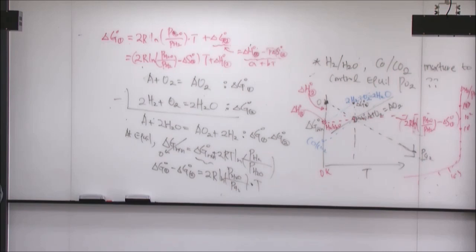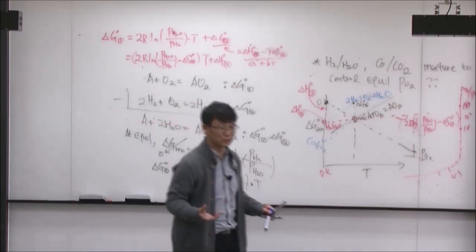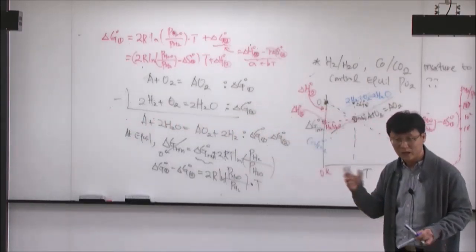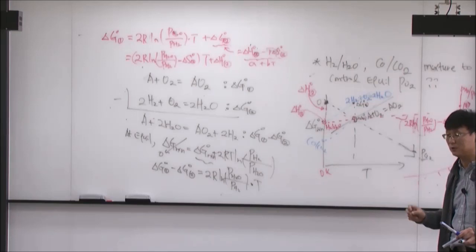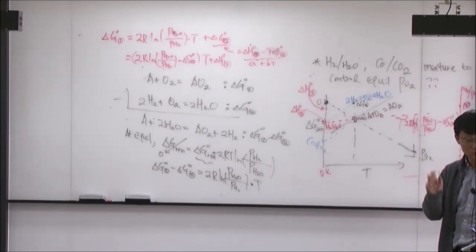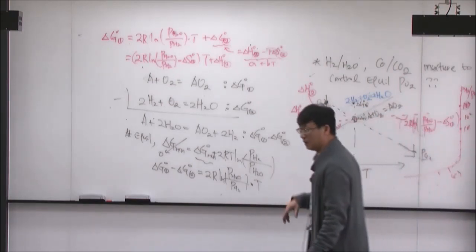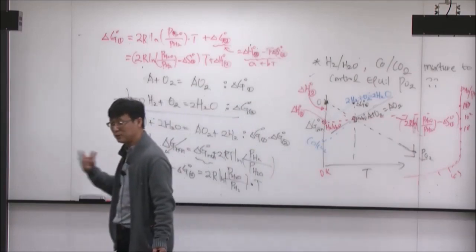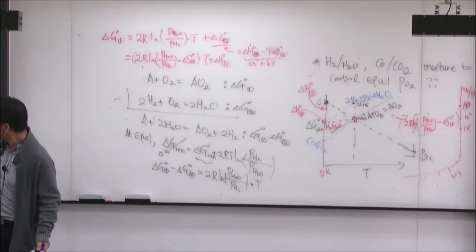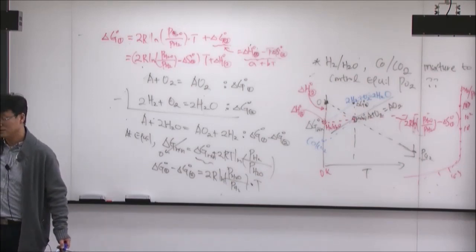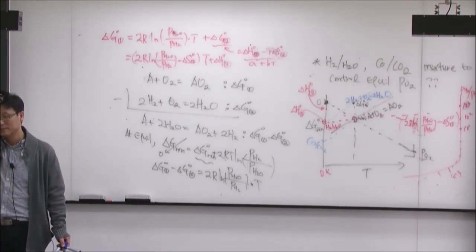So the Ellingham diagram is practically very, very useful, especially for the field engineer who doesn't have a calculator. They can directly tell how to control the partial pressure of oxygen, what the control value is, and how to control it by using CO/CO2 and H2/H2O. Also, when you produce some metal, what kinds of reductant can I add in the furnace to reduce those oxides to the metal, according to this balance. All of that information is inside one diagram.